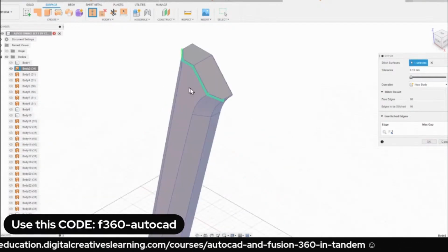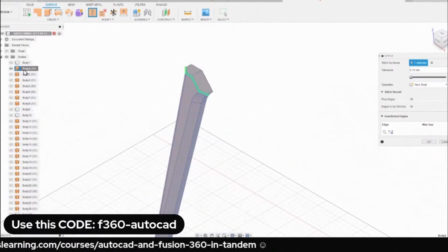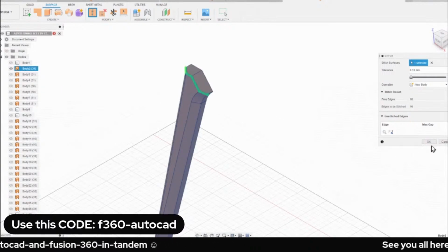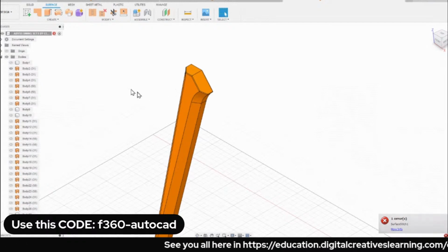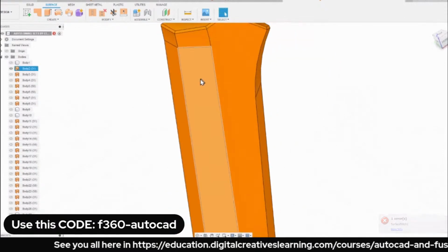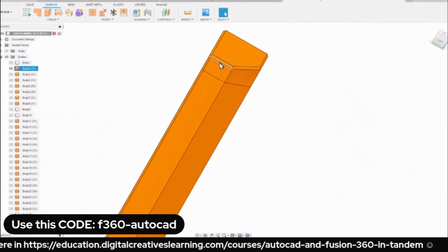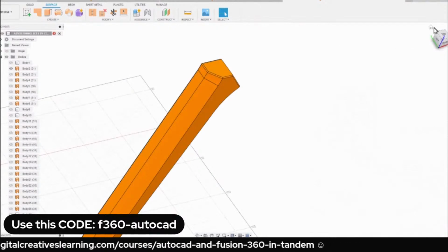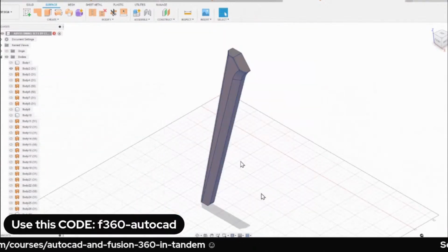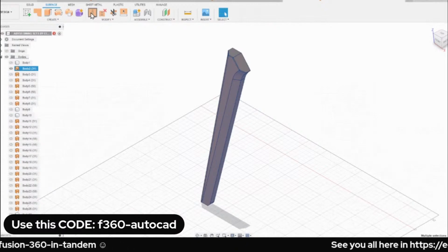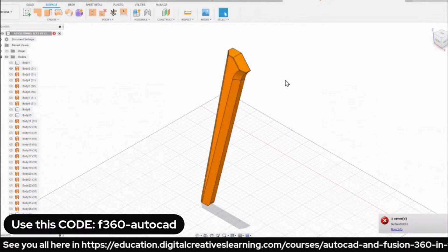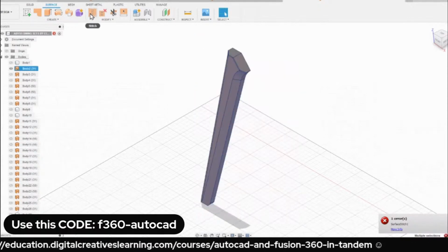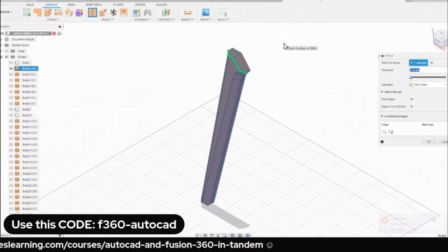It's looking nice. I'm seeing a green color. So take note, this is currently a surface. We're going to convert this hopefully into a body. Selecting OK. So the challenge here, it doesn't work. The challenge here is, of course, re-editing this surface, closing this up watertight for the stitch to convert this into a solid body. How about raising up the tolerance, let's say, to 0.2? Still doesn't work. How about 0.5?